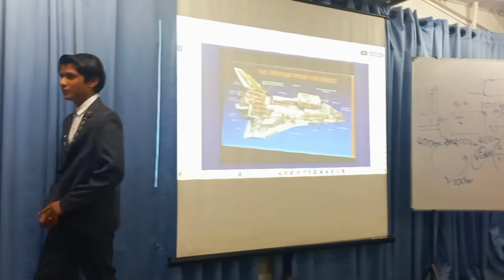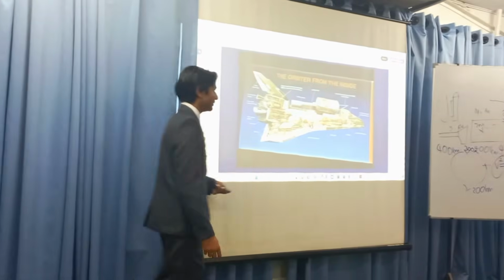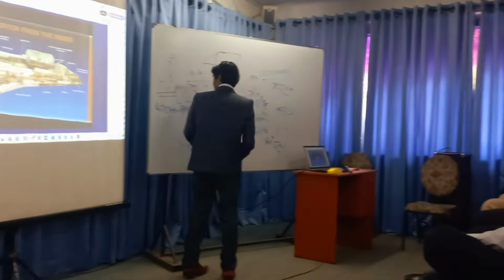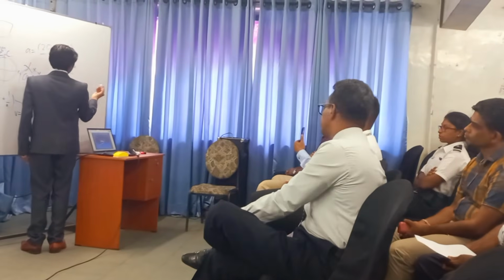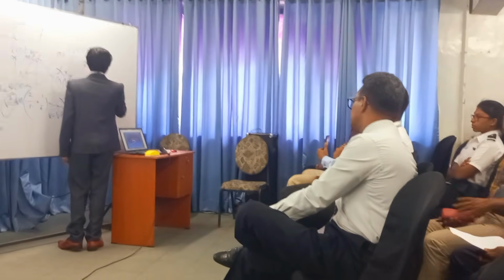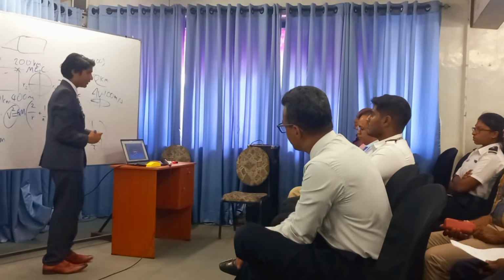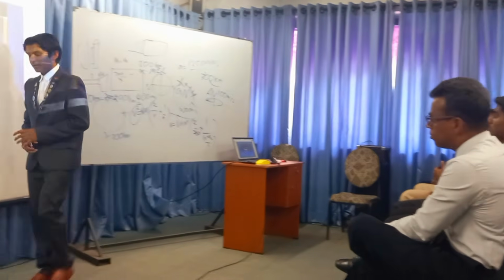In a jet engine, this is achieved by using the existing air of our atmosphere and then sucking it in, but the rocket does not have that limit, so it needs to use its own oxidizer. If we produce delta V of, say, 100 meters per second in the retrograde direction. The retrograde direction is the direction opposite to the orbiting body.